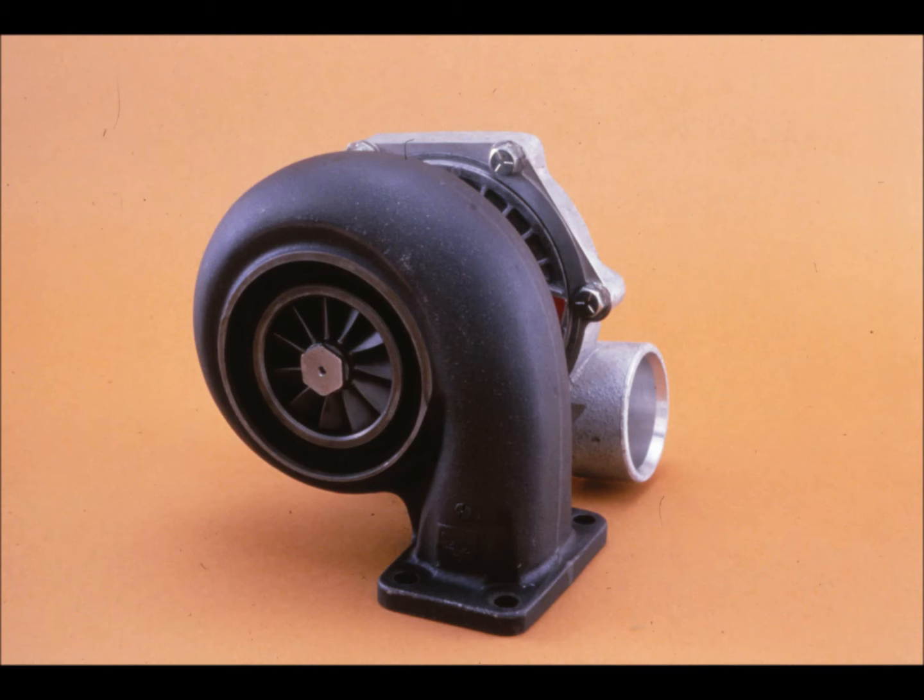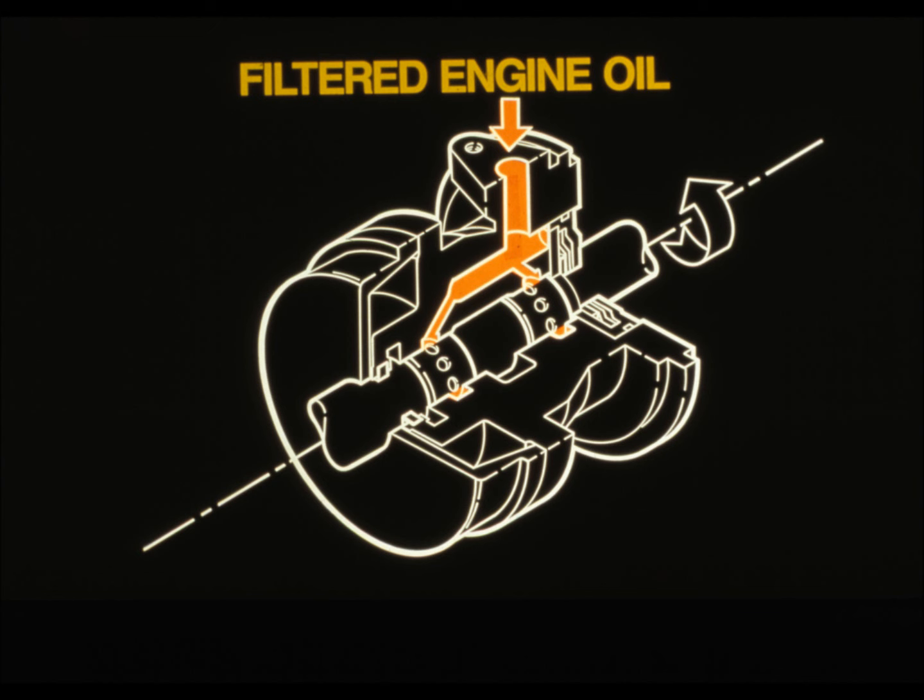All of the parts of the turbocharger are precision components, and they are manufactured to very close tolerances. Because of the high speeds and the heat and pressure of turbocharger operation, the bearings and shaft ride on an oil film. Clearance is built into the internal components to ensure that this oil film is maintained. A slight amount of play in the shaft that runs through the turbocharger is one sign of this clearance, which is necessary to assure proper functioning of the unit.